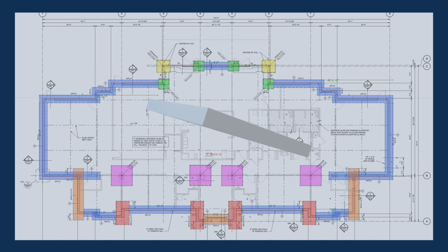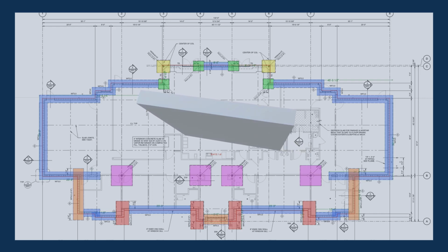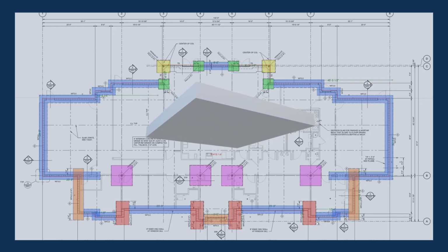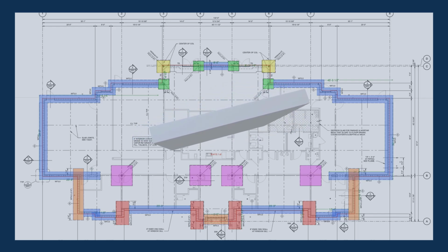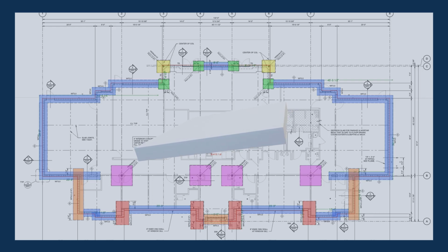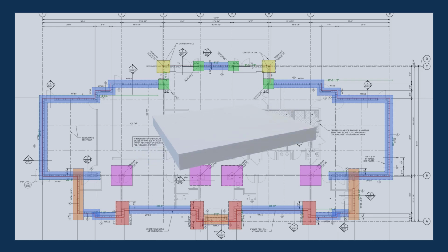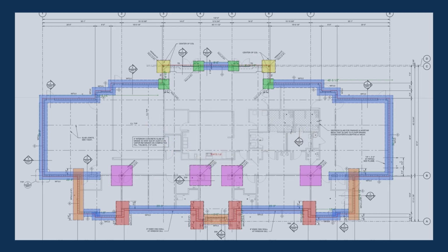Do you remember that number from before? That's right, 27. We know that there's 27 cubic feet in 1 cubic yard, so take your total of 128 cubic feet and divide that by 27. If you come up with 4.74 cubic yards of concrete, then you are correct. So, if your superintendent decided on placing just the F8 footers for today, we know now that we will need to order close to 19 yards of concrete including waste. And if you are pumping the concrete, add an extra yard for the pump.